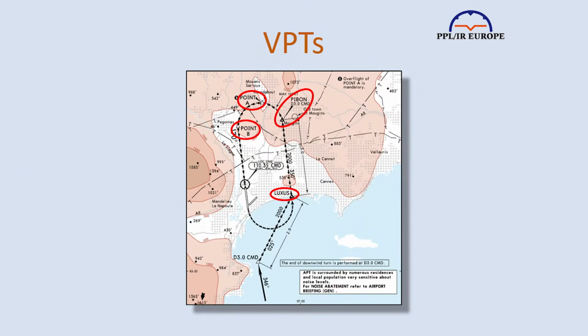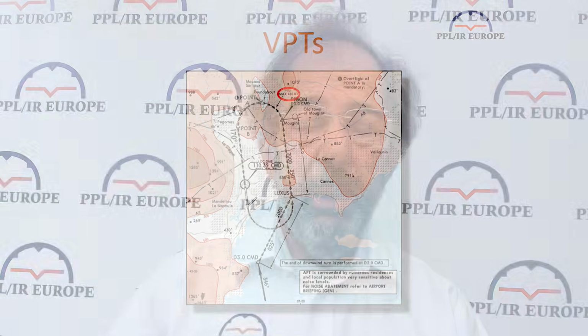A visual circuit normally allows some flexibility for pilots to fly within a general pattern around the airfield. However, in a prescribed procedure, the aircraft must follow a strictly defined route, often with specific turning points, altitude restrictions, and possibly even speed constraints. However, unless it's specified otherwise in the procedure, you're only required to maintain sufficient visual reference to follow the prescribed track. You don't need to be visual with the runway until you need to start the descent below MDA.